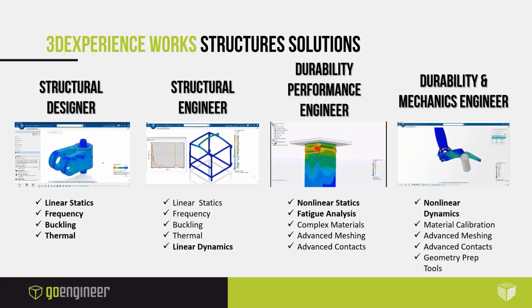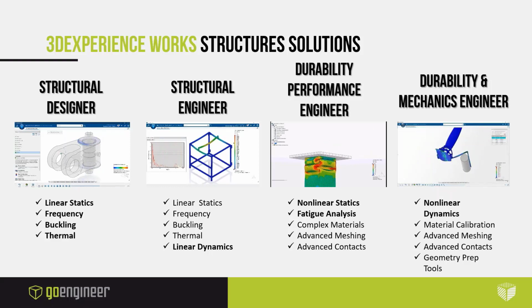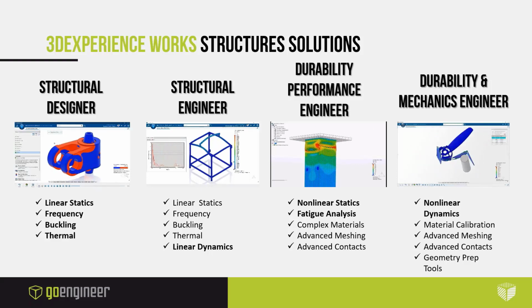Now, as far as the 3D Experience platform goes, there are multiple tiers of structural solutions that you're able to adopt. The design and the engineer tier gives you access to the Abaqus solver to solve linear statics and certain vibration problems. But when you get into the performance engineer and the mechanics engineer tier, that's where you get access to the nonlinear static and dynamic capabilities, where you're able to push the level of your analysis beyond an existing solution that you might have.